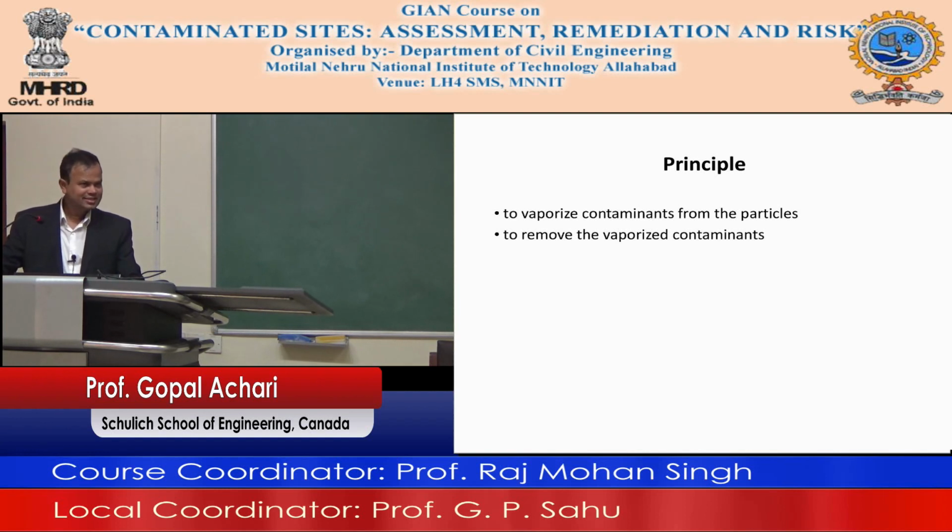But if it contains other stuff, for example, if you have a mixture of contaminants, let's say a mixture of certain metals and hydrocarbons, okay, you can use thermal desorption to get rid of the hydrocarbons, and then the metal contaminated soil, which you still need to deal with, maybe you can consider things like solidification at that stage. Okay, so it's a two-step process for the scenario that we just talked about.